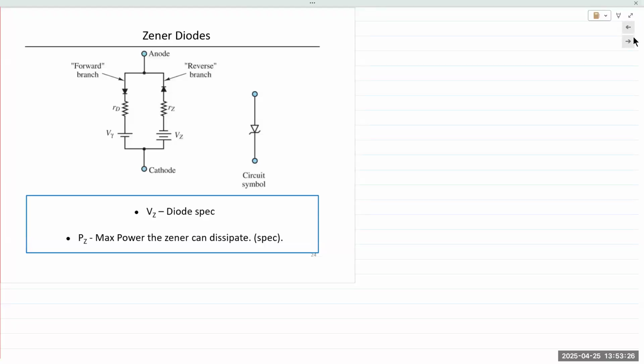If you apply an external voltage to the p-n junction, if you apply positive polarity to the p-type and negative to the n-type, we say it's being forward bias. If you apply negative to the p-type and positive to the n-type material, we say that p-n junction device is being reverse bias. And when it's reverse bias, it's completely off. No current can flow through except for a small amount of minority carriers.